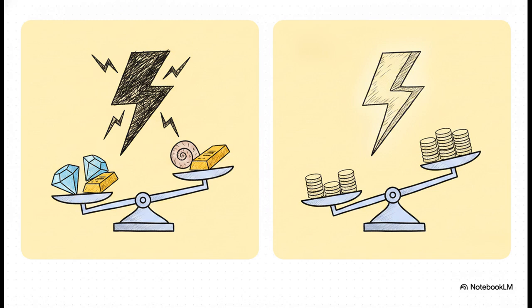Well, the power grid is exactly like that. You just cannot mathematically compare 400 amps sitting in an 11 kV zone with 145 amps in a 33 kV zone or 55 amps in a 132 kV zone. It's apples, oranges, and bananas. We desperately need one common scale so the whole system is speaking the exact same language.